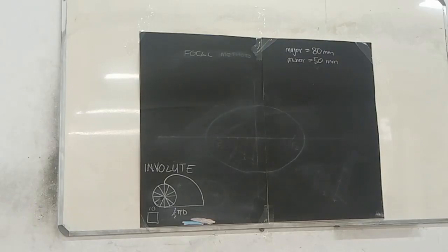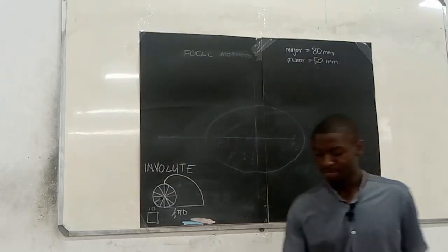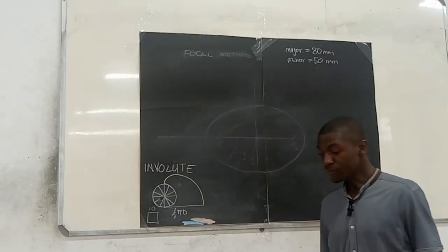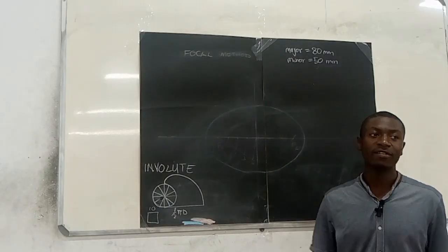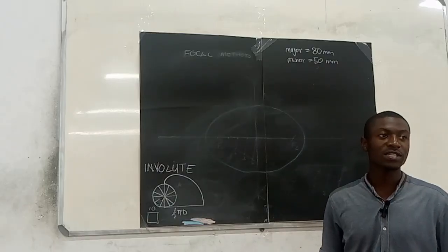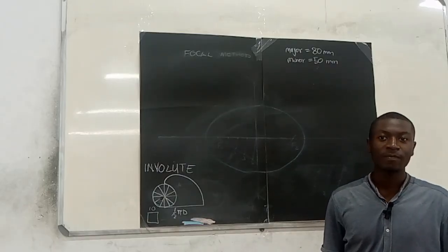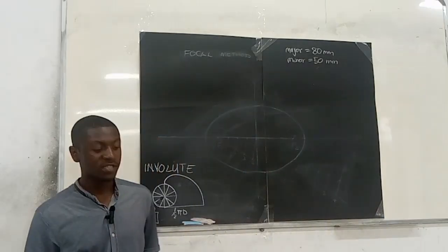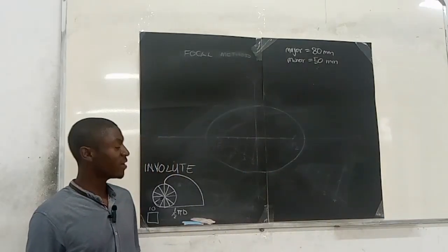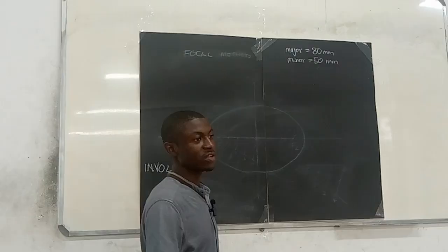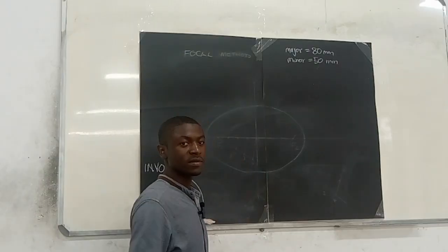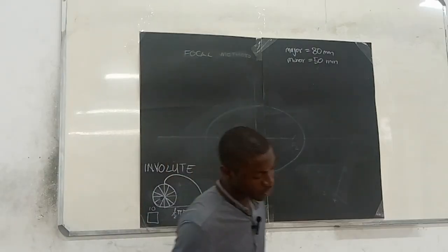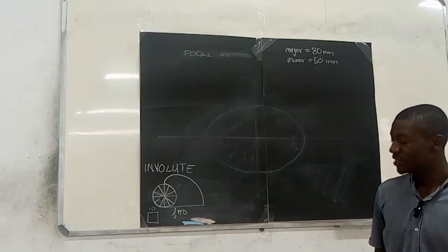From that diameter, how do we get the half point? It's 35. What's 35 divided by 2? 17.5. Can you measure 17.5 accurately in drawing? It's very difficult to get the midpoint. So what you do is, I talked about this. I actually did it here.